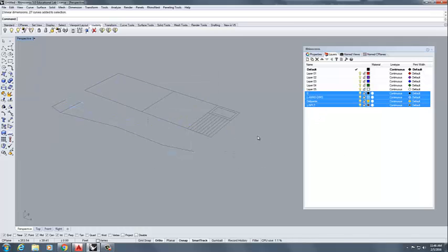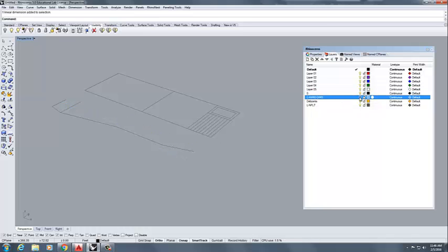You can also see they came in with their colors from AutoCAD, interestingly enough. They have the exact same color settings as they did in AutoCAD. So it's a good selection tool. I can turn the dims off. They really don't matter to us. So you can change the visibility by just turning the little light bulb next to them in layer properties off. On, off. And just navigate around, get a feel for it.